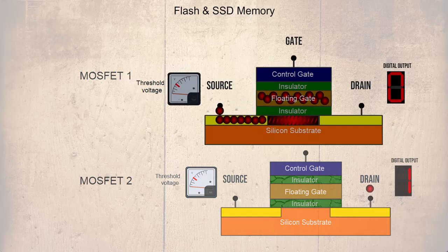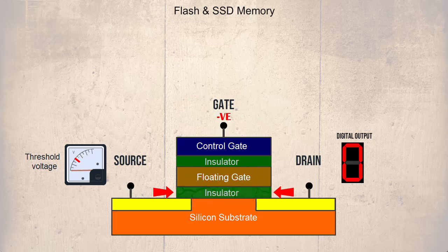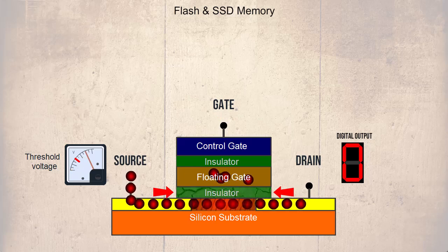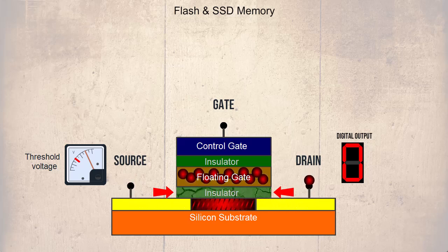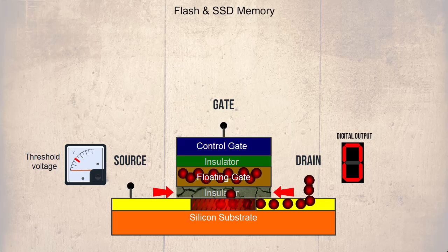One really important point here is that when a large voltage is applied to the control gate to repel the electrons back through the lower insulator, it is weakened. This also happens when a large voltage is applied to the source. So we can see the end result is that the lower insulator will ultimately fail, which means the gate will not be able to hold its charge, corrupting the data. Again, we are only looking at one single bit.